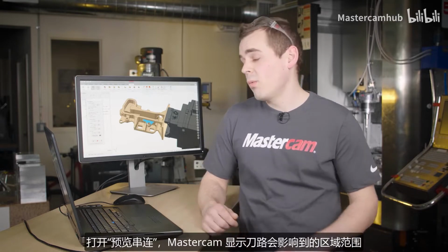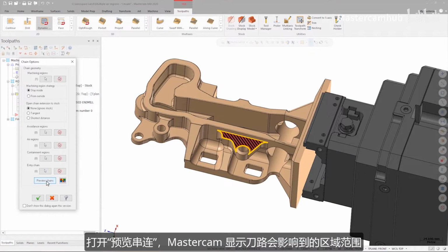Using Stay Inside keeps all the toolpath motion inside the area we chained. This strategy is useful for machining pockets or times where a wall or boss is right next to the area we need to machine. To help visualize how Mastercam will process the chaining options I've chosen, I can use Preview Chains. When I launch Preview Chains, Mastercam temporarily color codes the area that will be affected by my toolpath.